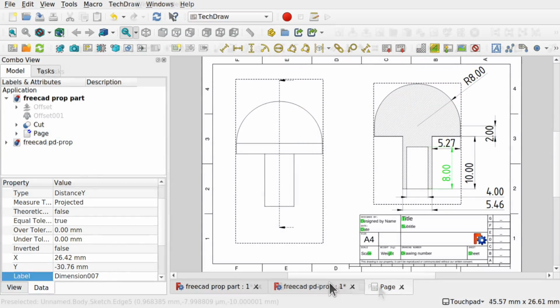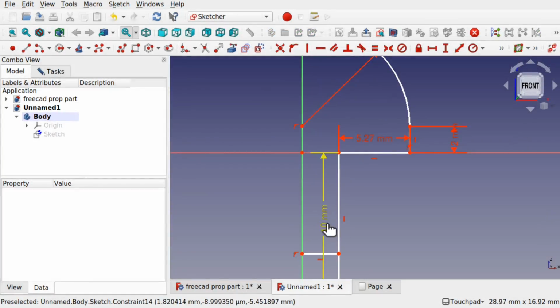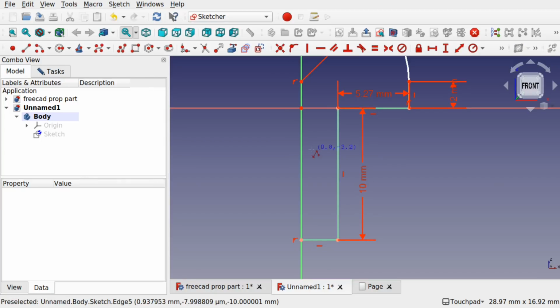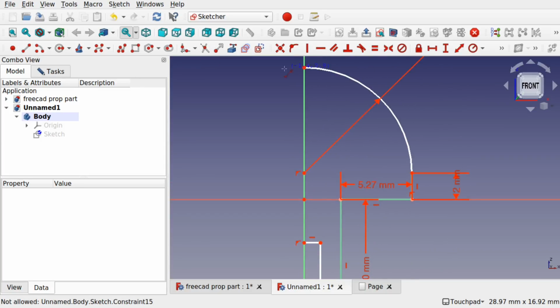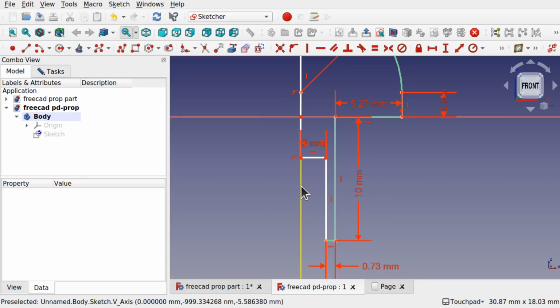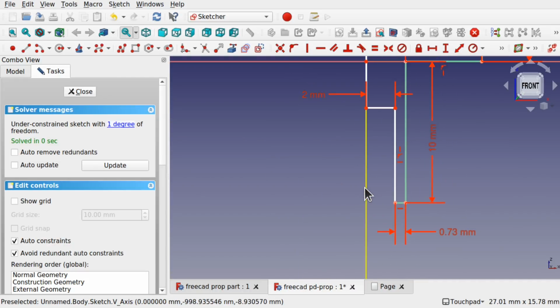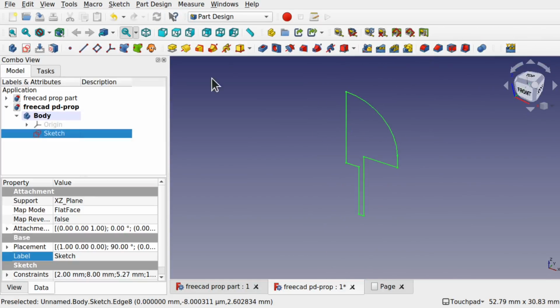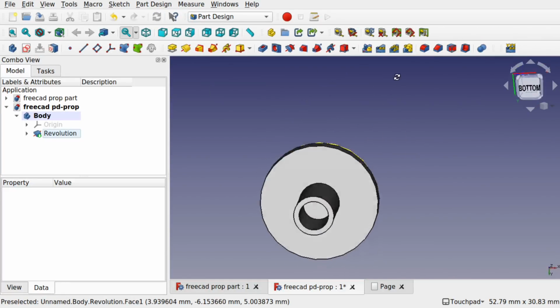You can see how this object is being built up quite quickly, using the constraints in there to fully constrain the model down. And we're creating one side of the profile and also the inner part that will be a void in there to allow for us to connect that to our toy. And then all we have to do is select that sketch and create a revolve from there once all the constraints are in. So it's a very simple process, a single action, and it doesn't take long to create. And we have the finished product.